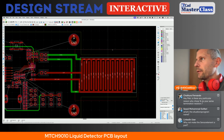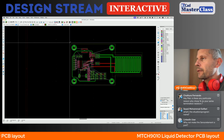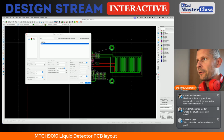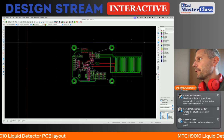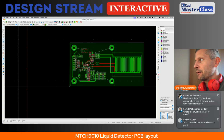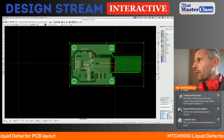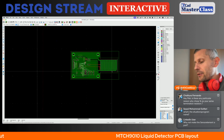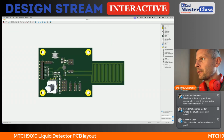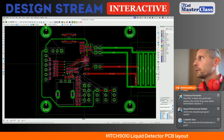Okay. And if we are talking about the ground plane, I can design this polygon, thermal reliefs, okay, below the entire PCB, and because we just defined the rule area, the copper pour will not be applied here. So this is the top layer, here is the bottom layer. Let's continue with the layout.